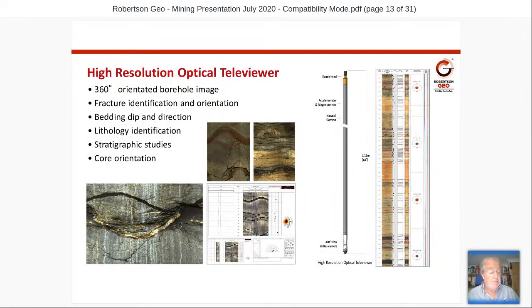So there are two main types of televiewer currently in use, and obviously this technology has moved on dramatically in the last 10 years or so. And as a geologist, to get a picture of downhole conditions and the downhole formations is invaluable. To see quite clearly the thickness of the beds, the degree of fracturing, some of the smaller features. You can see in that bottom left picture some infilled veins showing through there.